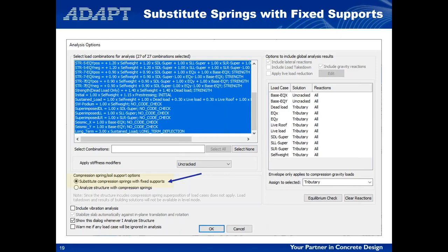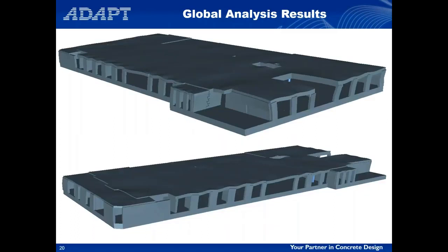Once we've done that analysis, here are some images of having run this concrete podium box. Now remember, the superstructure that we don't see is not explicitly modeled in Builder, but we've applied all of the couples and the base shear, so you can clearly see the lateral deformation in that structure.